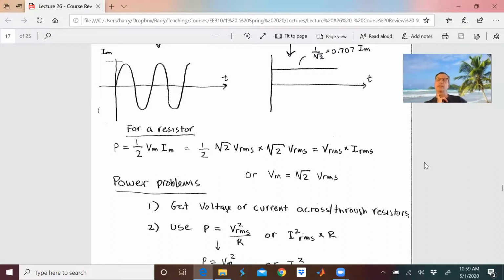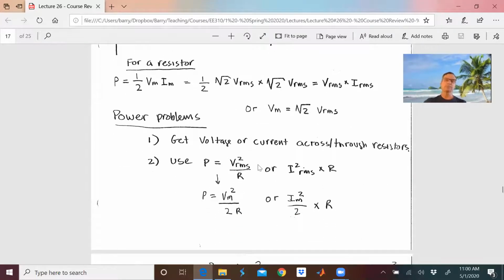A cool thing is that our modern AC voltmeters in our lab, I say modern because in the old days they weren't, are actual RMS meters. They do that integration for you. So you can put whatever kind of waveform you want in there, and provided it's within the bandwidth that that meter can handle, you're going to get the RMS value. It's pretty cool.